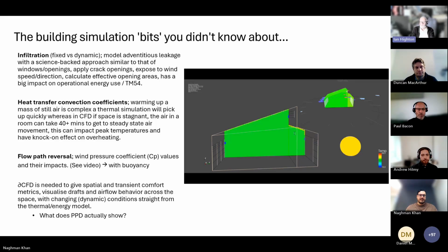But when you look at a real building, if the wind's coming from the east, those east facing zones absolutely get hammered. And on the west zones on the opposite side of the building, all that air has traveled through the building, it's got warmed up or cooled down by the plant, and as it's coming out of the building, there's absolutely no load on the other side.